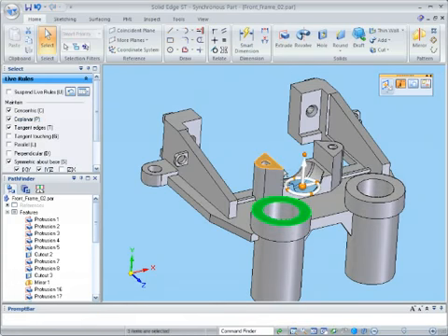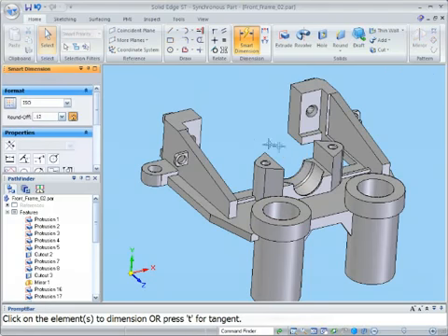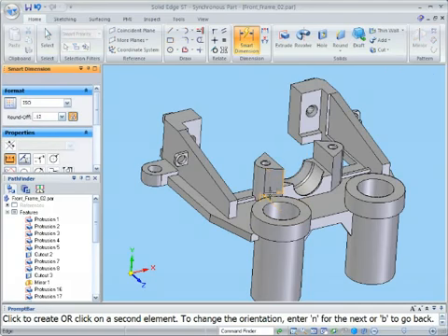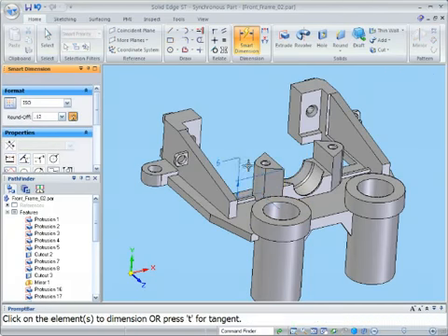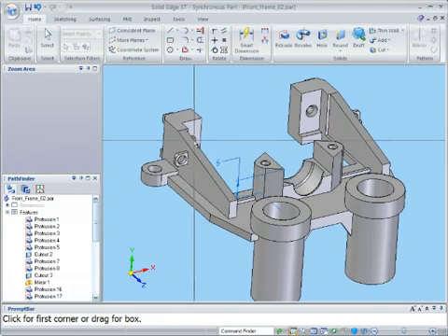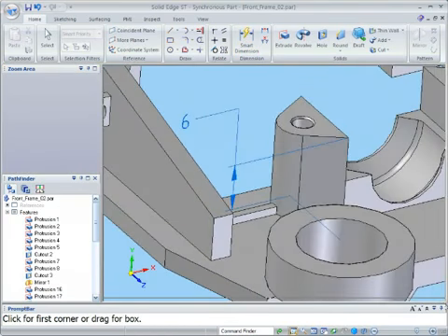Now select the primary axis and drag it to the new key point on the reference geometry. I'll add a 3D dimension so you can see the new distance is in fact 6 mm. Following these techniques will shorten your learning curve and ease your adoption of synchronous technology.